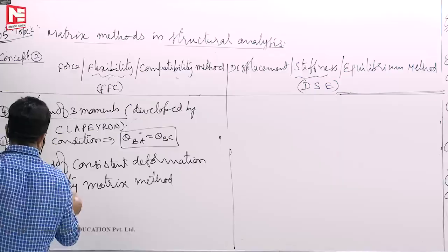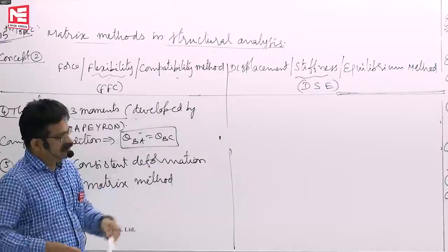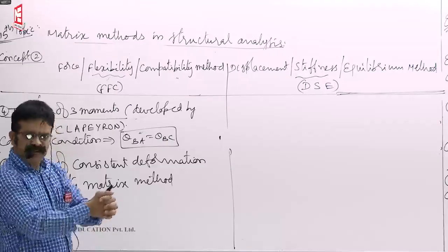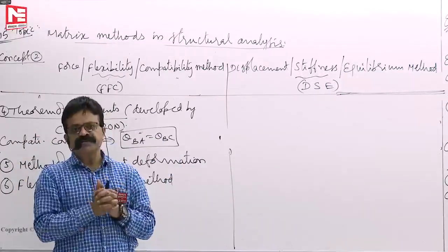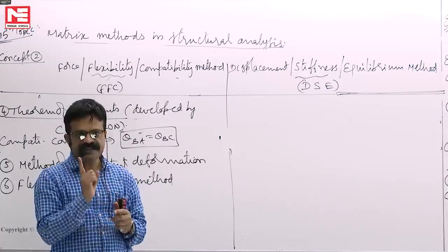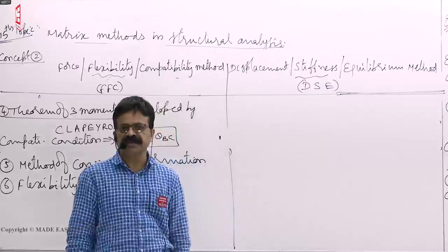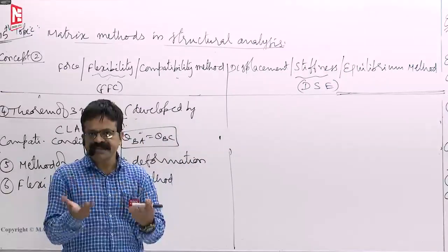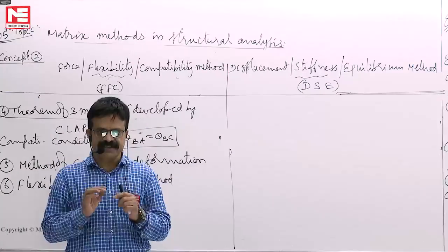In all these cases which we have studied in strength of materials or two hinged arches, or you are going to study in matrix methods, the Ds value must be less. Suppose Ds is 1, then you require only one compatibility condition as in those problems. As Ds increases, the number of compatibility conditions also increases, our work also will increase.